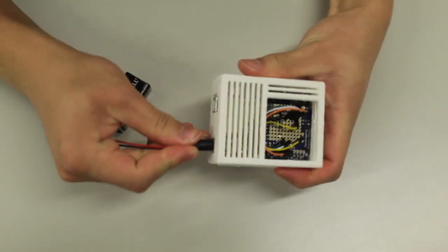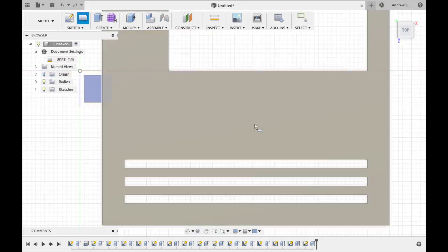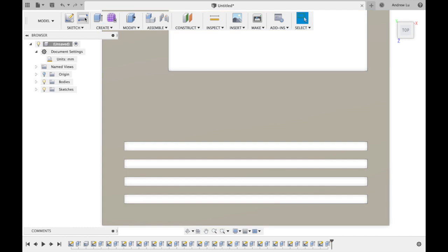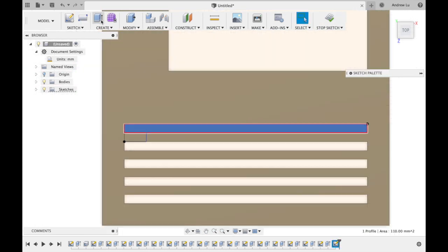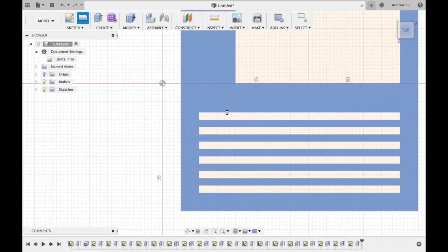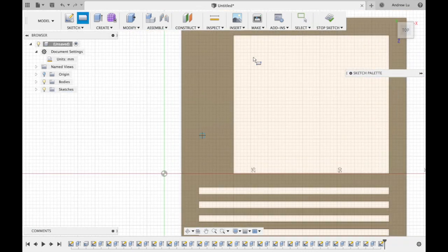During the design process of the sensor case, we took many factors into consideration, including ventilation, locations of the ports and SD card reader, and the location of the temperature and light sensors. Based on this, the design of the sensor case incorporated slits throughout both pieces of the case to ensure that there's sufficient airflow while the sensor was operating.